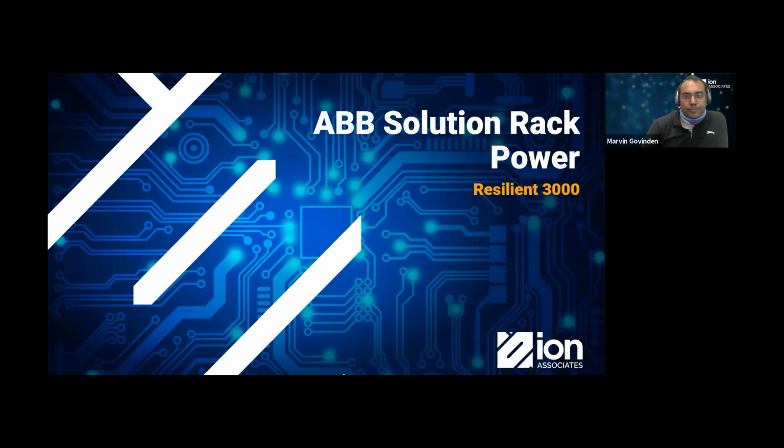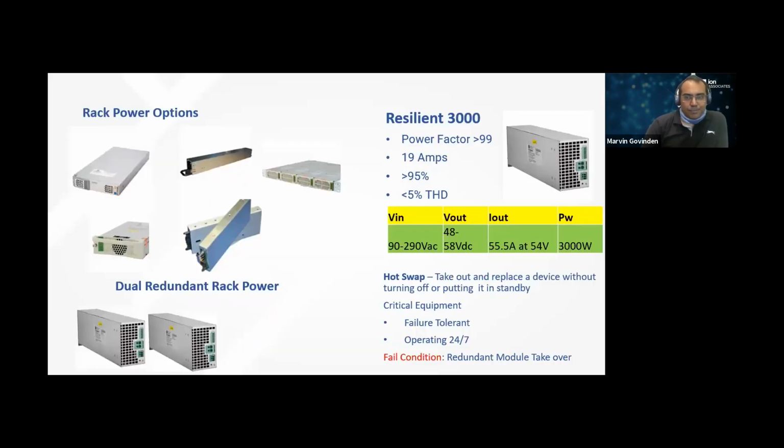Rack power, if you have data centers, telecoms, telcos, they're going to need some high kilowatt power supplies, and we need to distribute power across that rack. And so we have lots of different solutions which will accept AC and will give out maybe 48 volts DC that you need, but in terms of kilowatts, and that's distributed across the rack. A lot of the times you want these things to be dual redundant. So if we need to pull one out for whatever reason, we can hot swap it and plug another one back in. So we have these things available as well.